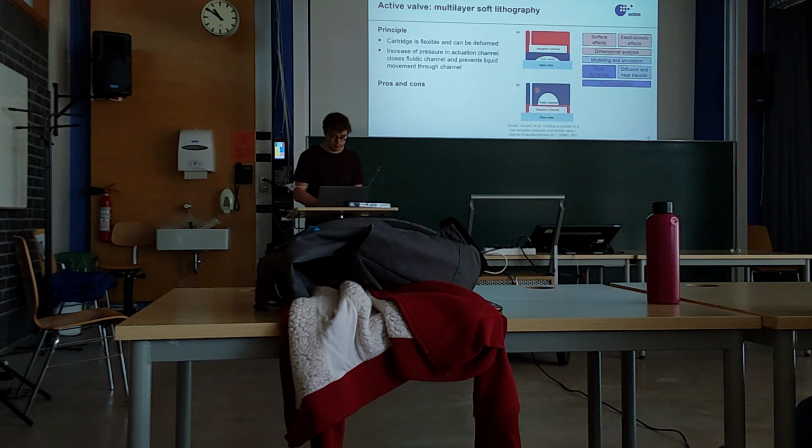If you look at the bottom, it's the inverse. You have a very thin film for the actuation element, and by, for example, heating up this actuation channel, you can push this thin film right along your microfluidic structure and thereby close the system. Compared to the other two approaches, this is very reliable. If the channel is closed, it is closed, and it's impossible for liquid to move through your channel.